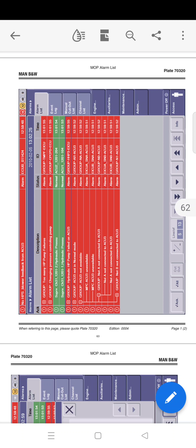So that can be done from the operator or from the chip level, from the acknowledge all button. So we can see acknowledge and all on the tick mark given. If you press acknowledge and you select some alarm, the individual alarm will get acknowledged. But if you select all, all alarms which have become normal will get acknowledged.